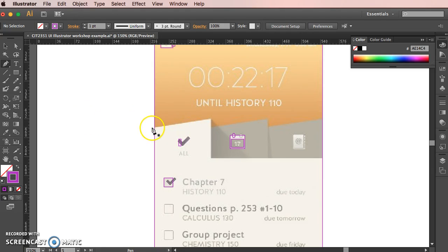So what I'm going to do is come over to the edge, slightly past the edge. You could start here, but I prefer to start just slightly off screen. I'm just going to guess with my eye roughly where I think that line would go. I'm going to come up here to where I think the corner is and click. And I'm going to hold down Shift. And with Shift, you can see I've got smart guides. As I move down, I get this little green line.